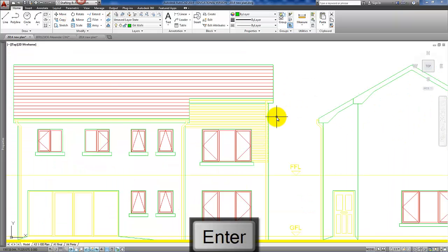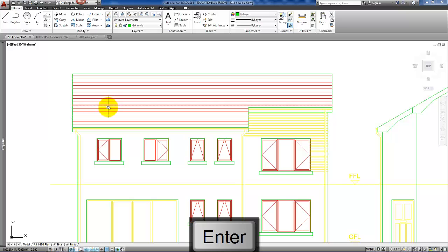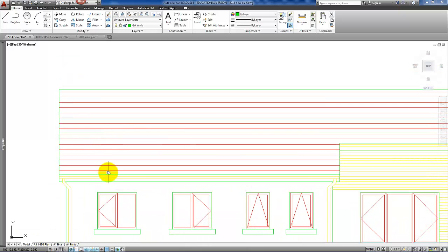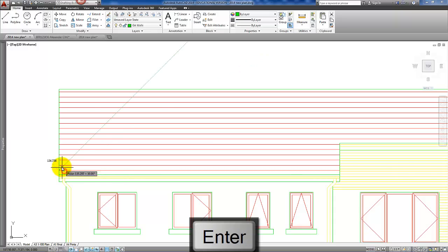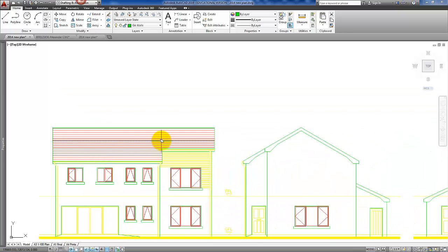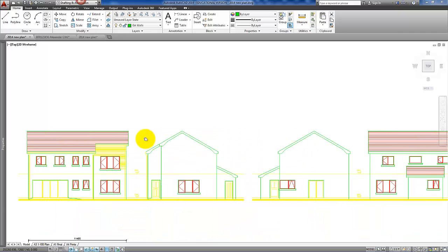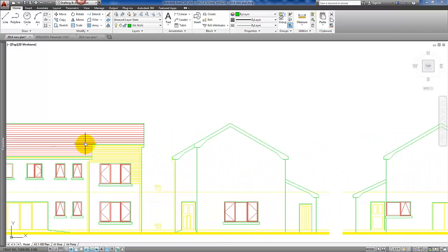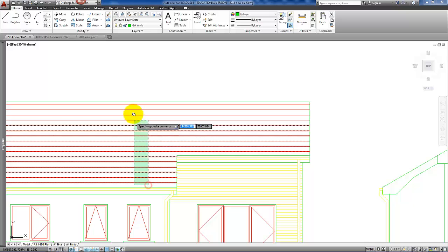like so. And for the roof itself then, we do need to indicate that it's a tiled roof, so the lines need to be shown on the roof there. Now what is the distance that's being used between those lines? 150. Okay, so basically if you're wanting to do that, it should really be on the roof layer, which it wasn't in this case.